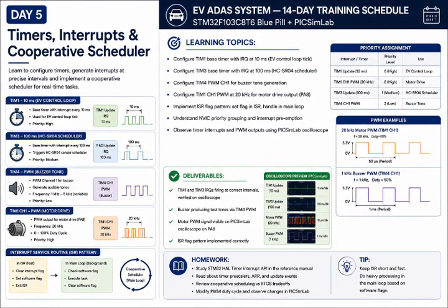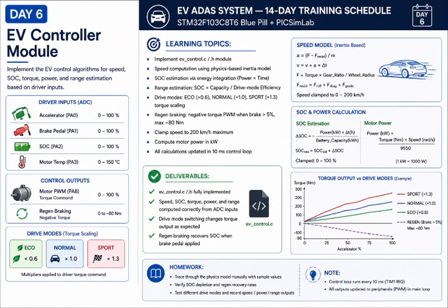And coming to day 5, I learned STM32 timers, interrupts, and cooperative scheduling. Different timers were configured for the EV control loop, ultrasonic sensor scheduling, motor PWM, that is pulse width modulation, and buzzer generation. I also understood interrupt service routines (ISR) and how embedded systems execute multiple tasks efficiently without an RTOS.